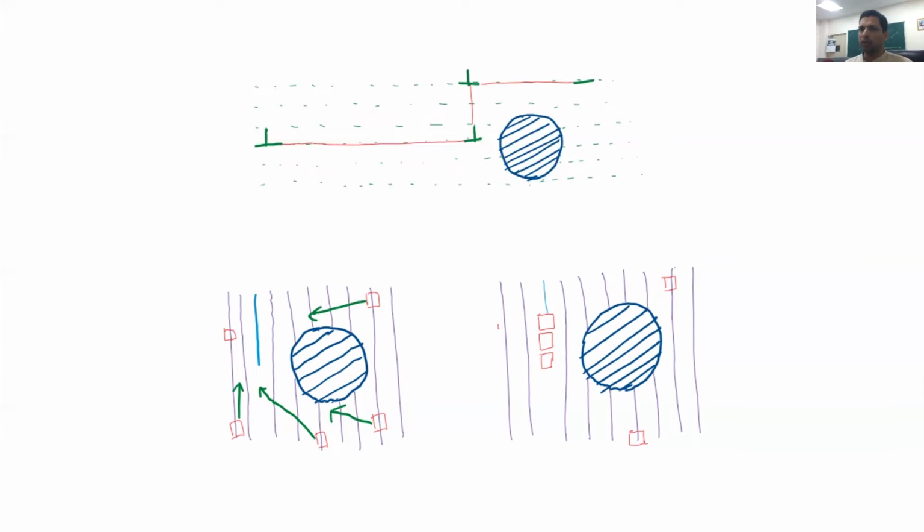So after some time, some of these vacancies would have moved over here. And what this does is cause the climb of the dislocation. So this is the de facto climb of the dislocation. Here, the dislocation was here, and now it has jumped all the way up to here. And similarly, after some more steps of jumping or climbing, the dislocation may reach here, and then the climb force may be sufficient to push it over here, and then it can move freely. So you can see that the rate controlling step is the climb of the dislocation, and thereafter the dislocations glide.